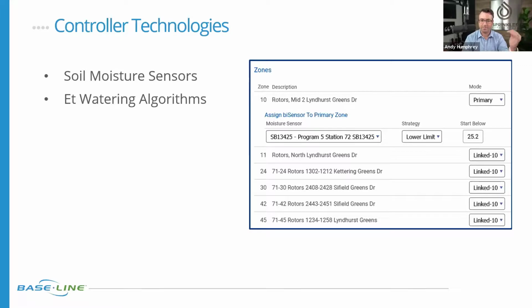Then based on how much it rains and what the soil moisture sensor picks up and reads, if it has reached field capacity, then we'll stop. So it's like this two-step automation: pause, see the results, and then either stop, or if not, resume. Right, so that's really the two-step: pause, take a look at the data, then either resume or stop based on actual soil moisture absorption.